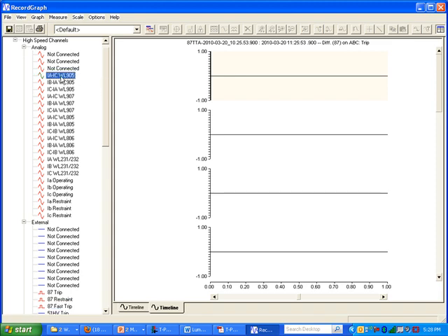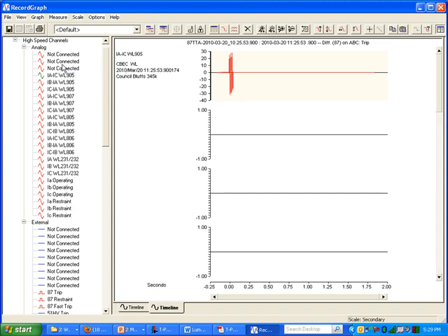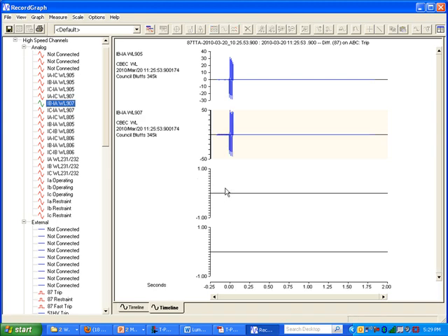All your currents should add up to 0. By putting them in this way, you can easily add them up. The other thing you can do is also see if the currents are 180 degrees apart, whether all the currents going in must equal all the currents going out. So it's a very nice way to analyze differential faults.